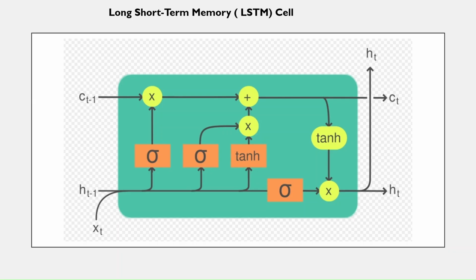Here is an example of the LSTM memory cell. In the LSTM memory cell, we have 3 sigmoid functions and 2 tanh functions, which, when we try to implement them, require a lot of lookup table resources, as we'll see in the following slides, which was too big to be implemented in ASIC.